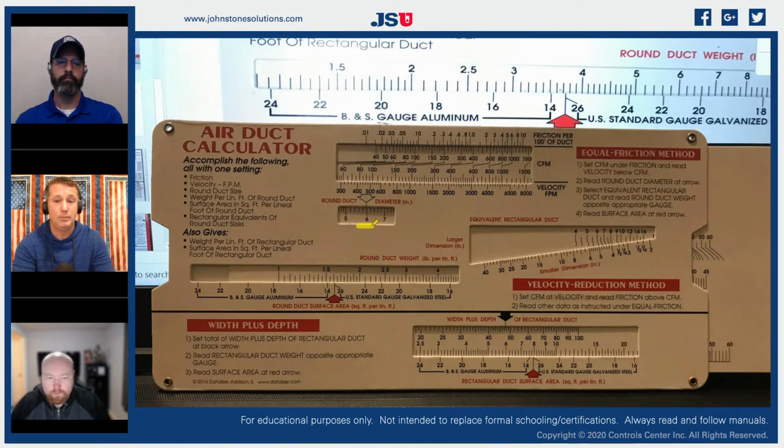6-inch round. By the way, how much airflow can I put through that 3.5 inch? At the same equivalent, it would actually be 3.5 by 9. So 6-inch round is the same as a 3.5 by 9. It's probably going to be a 3.5 by 10, but 3.5 by 9 is the actual calculation for that. So if I wanted to run the equivalent of a 6-inch round through a wall, I just needed to have a 9-inch wide cavity. So remember me saying that I set most of mine at 0.1 inches. So I'm going to set most of my calculations at 0.1 inches, right there.